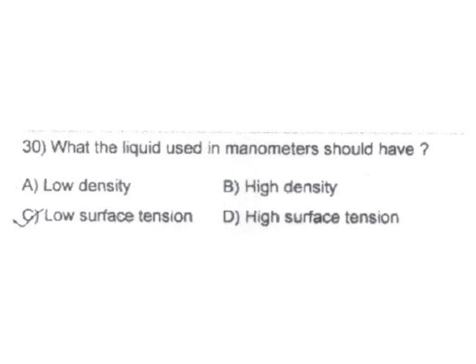What should the liquid used in a manometer have? Manometric fluid properties. It should have low viscosity, then low surface tension, then high boiling point.